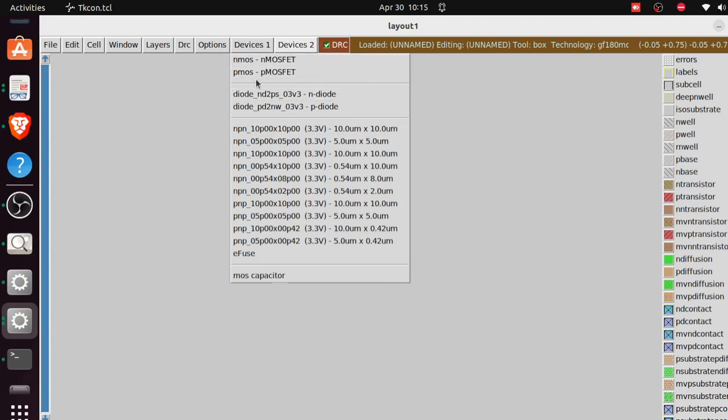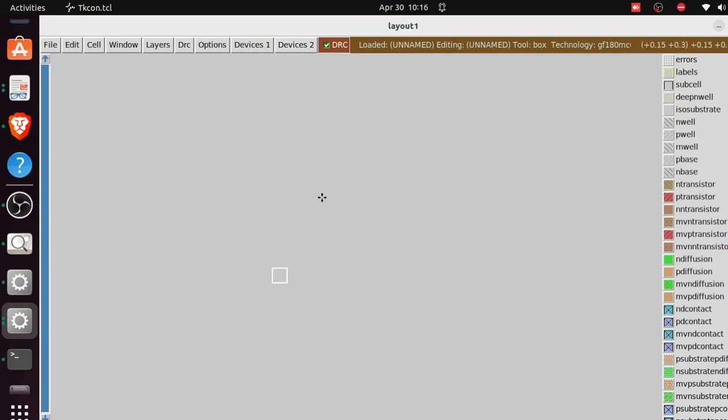But you can do SPICE-driven, netlist-driven layout, which is what we're going to do here. It's much easier because Magic imports all the devices for you, and you just start with routing or wiring, unlike the pixel-based approach where you have to bring in the components yourself before wiring.